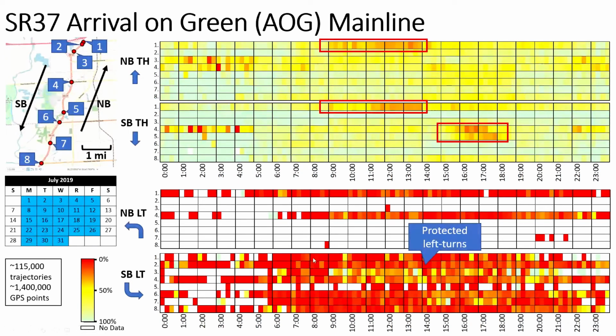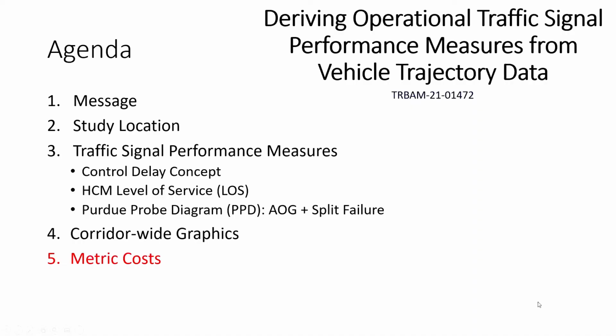For the left turn movements, you see here there's a lot of red, but not to be alarmed, because a lot of these left turn movements are protected only movements where the coordinated phases aren't really timed for.